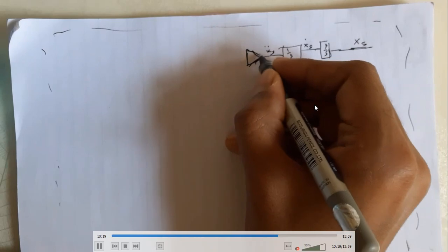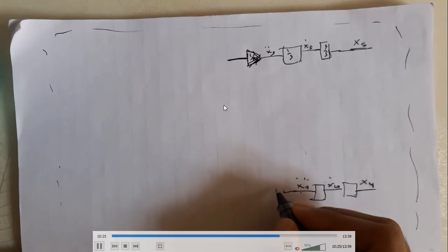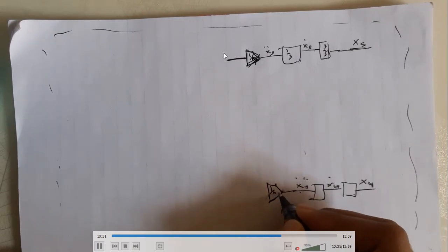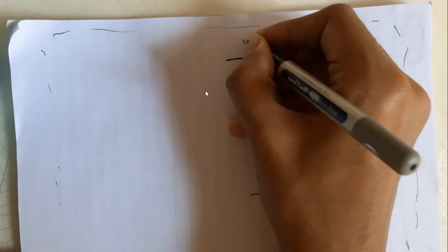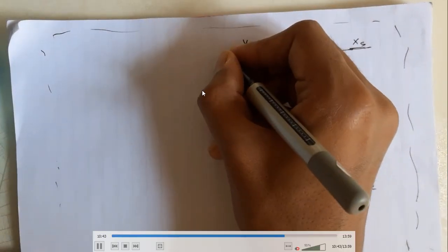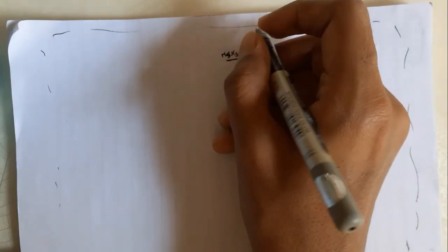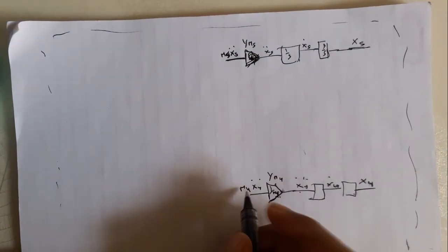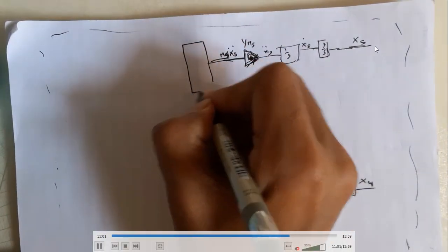So I will do it in MATLAB. It is very clear, just for the understanding's sake. Now what we are doing is we are multiplying this 1 upon this value to xs. So here it will be ms into xs double dot. Multiplying by 1 upon ms here, and here it is 1 upon mu. So this value will be ms xs double dot. I'm trying to show you in a backward manner. Originally it's done on the opposite side. So I'm showing what our output is and what we need to do to get our input.